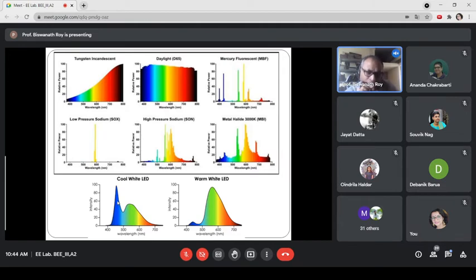Some yellow color tinge is visible. That is actually the color of the phosphor material. That phosphor is excited by the blue. Okay, and in turn, by photoluminescence, the phosphor emits this kind of spectrum. So this spectrum is actually contributed by this phosphor material, and this is contributed by the blue LED chip, and these two make white LED light.